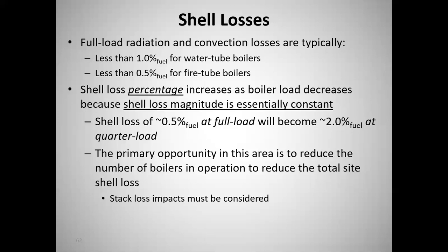So when they get a load of tires in there and start cooking them, they control temperature by steam pressure. If something happens to a boiler and they lose steam pressure or they change steam pressure, they get a change in temperature. Well, if they get much of a change in temperature, it can potentially affect the quality of the tire. And so they are extremely paranoid about their boiler pressure.